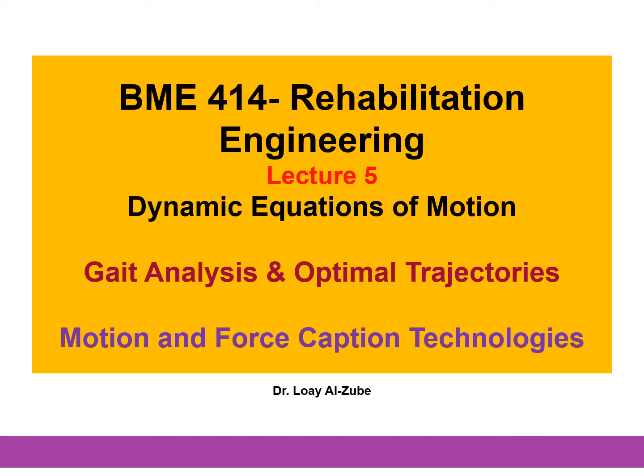We are still finishing solving the equations of motion. Step 1 is building our idealization, the model. Step 2, constructing the equations of motion, and we have two ways: you either use the Newtonian force approach or you use the Lagrange work energy approach. And step 3, solving the equations of motion.